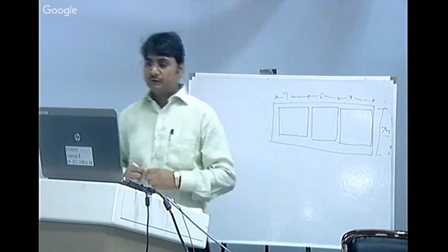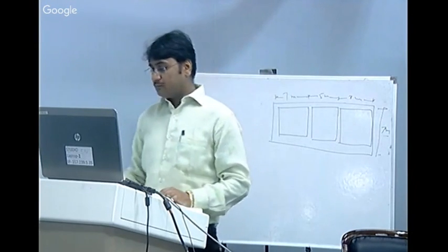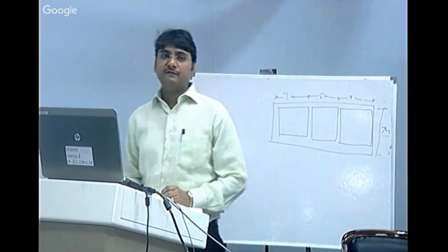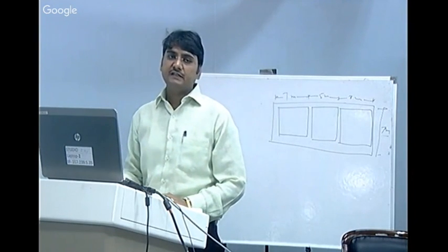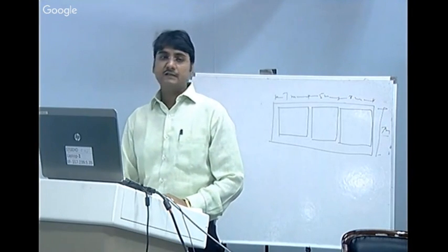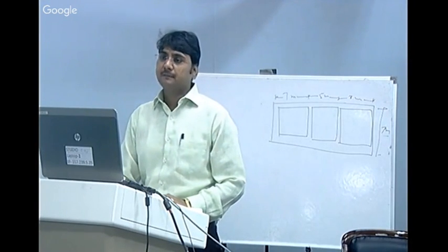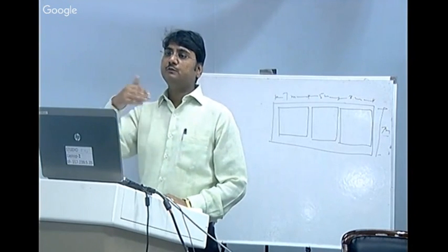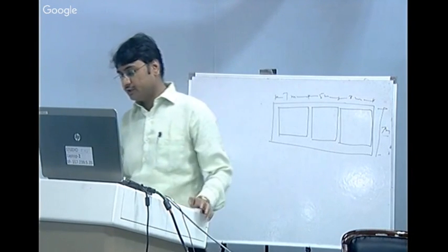So you need to calculate the mass of each story. Now you are having the 3-storied building. On each story you need to 1 multiply by 20 multiply 7. It is around 140 tons. And then you need to multiply it with 3-storied.